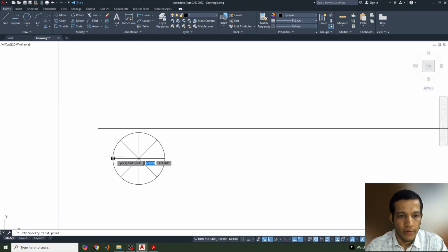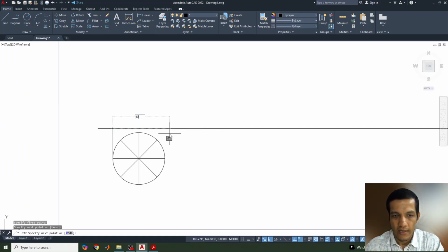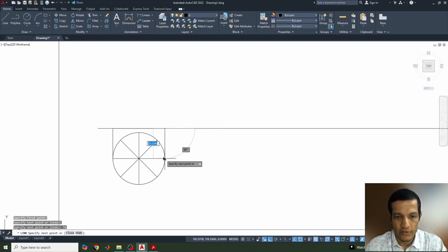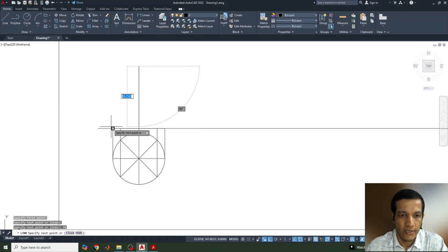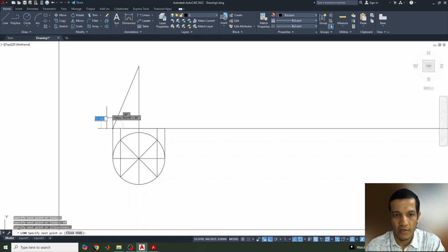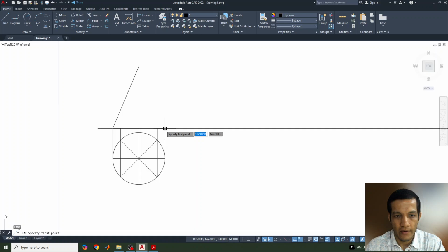So now from each of the points we just need to draw the vertical projector lines and we can join all these sides. Okay. Yeah. And the axis height is given 60, so I'll take the 60 height axis and I'll just join it here. Okay. And from here also I'll join it and I'll join this one.